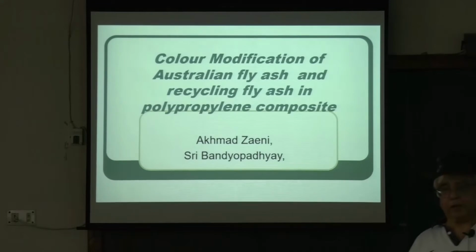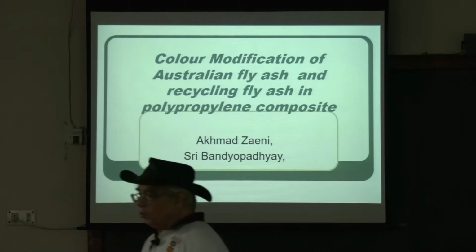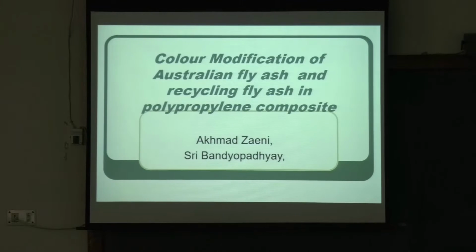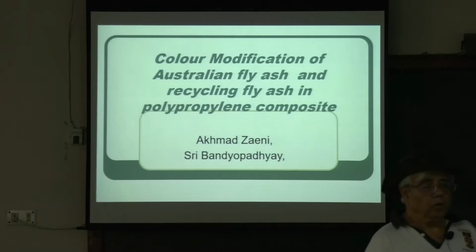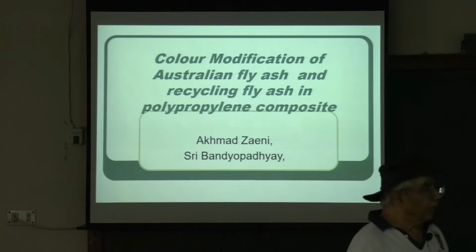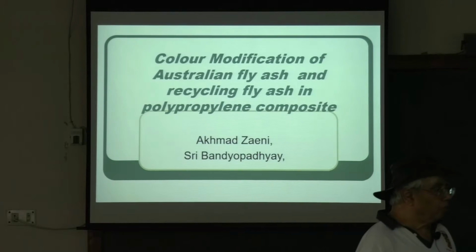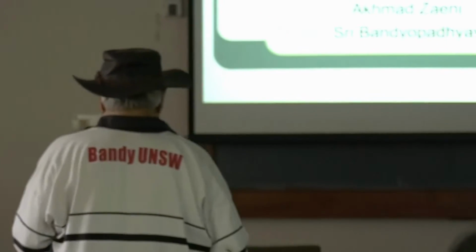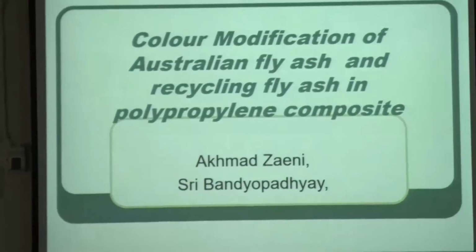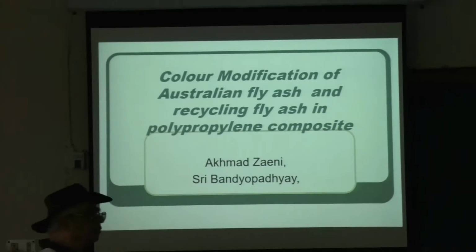Okay? So I thought we have done that, and you see the strength of the polypropylene, some of it goes down. But I thought in the final lecture, I'll show that even like fiber composites, you can also put a coupling agent on this fly ash, because fly ash is also kind of ceramic. They are not all glassy. Only one or two components are glassy, but they are all crystalline part. But they are still ceramic. The advantage of a coupling agent is that it makes the matrix and the fiber friendly and attractive. And stress transfer and strength transfer can happen without any concentration. So some of the slides in this one have been shown, but now we also include the slides using the coupling agents. All right?